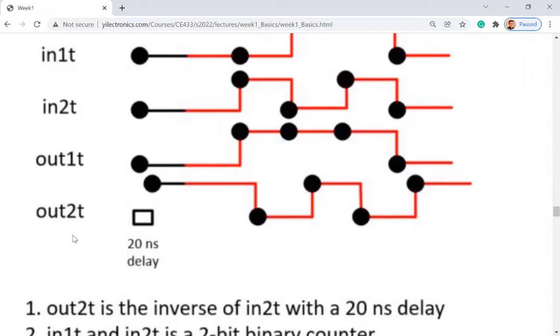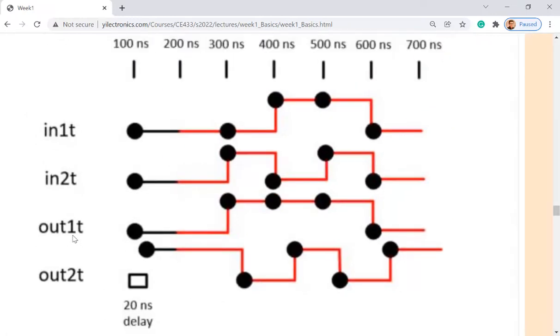And now let's see. There's a little error here. So this is what I drew, okay? After I had that simulation test bench, you can actually predict what you are going to get. So that's what I drew here. These labels are a little bit incorrect. So this should be 0. I should actually shift all the labels to the right-hand side by 100 nanoseconds.